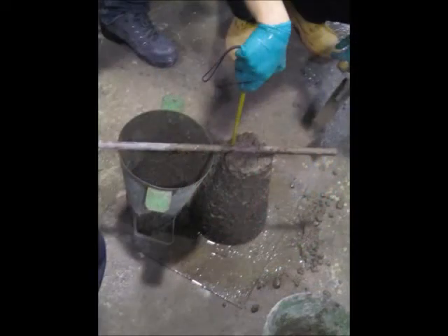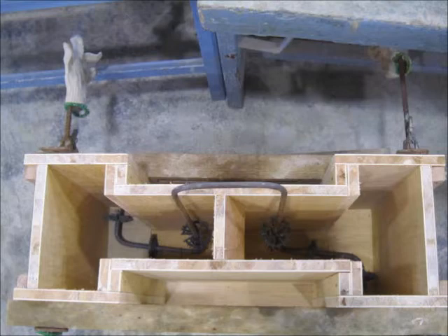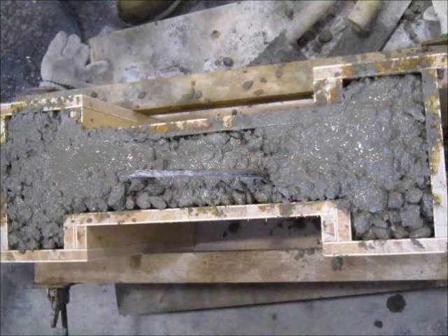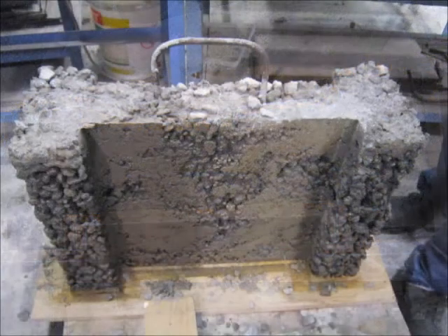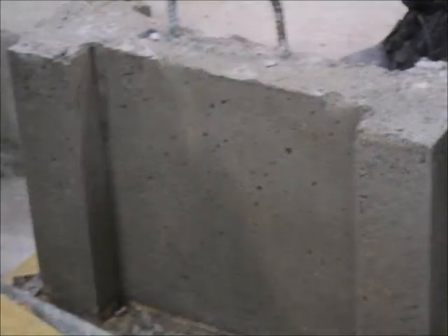We do some tests to test the quality of this concrete. Before concrete casting, we used to check the formwork and steel reinforcement according to the drawings and requirements. After concrete casting, we must minimize air contact in the concrete, so as to reduce air voids and make the concrete dense, so that its performance is better. Therefore, compacting is important.